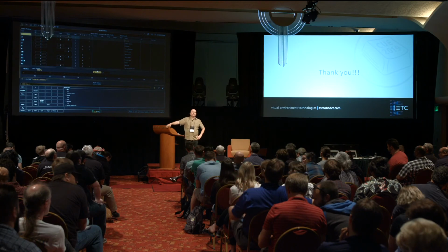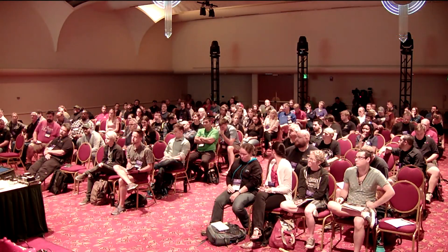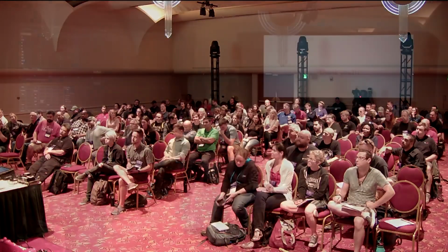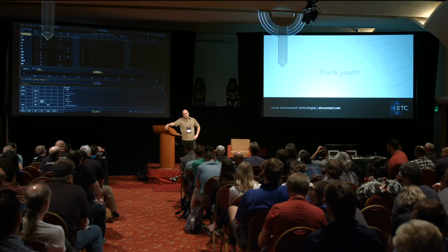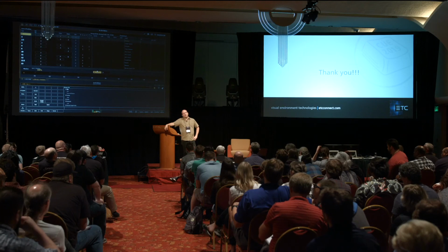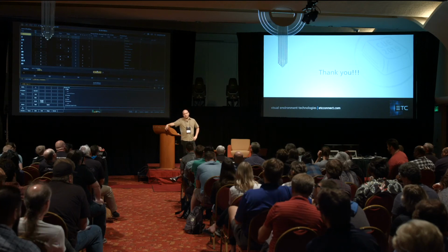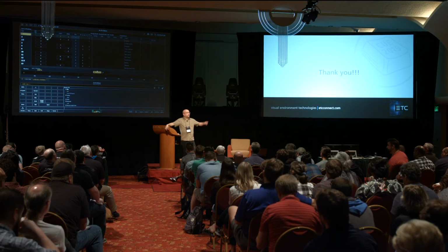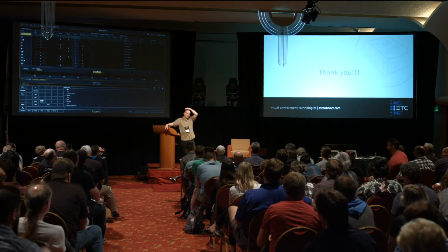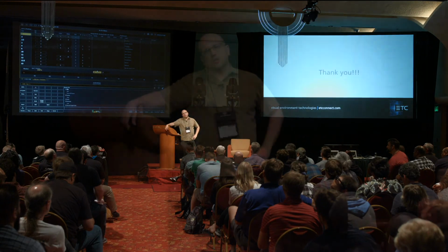Yes? Oh, that's an interesting question. Is DMX ever really going to go away? Of course, that's a personal opinion. My personal opinion is no, because DMX connectors are really robust. Network connectors are not. DMX runs in a daisy chain, which is very convenient if you're trying to run things along a pipe. Network does not. So no, I don't personally think DMX ever will.